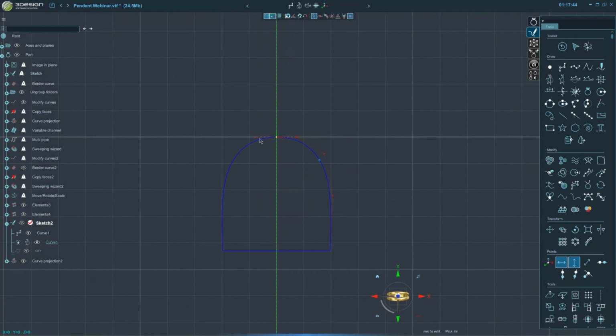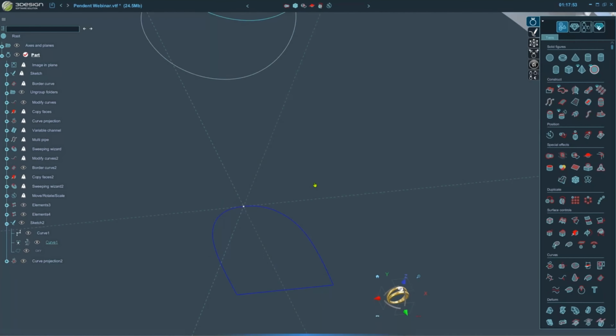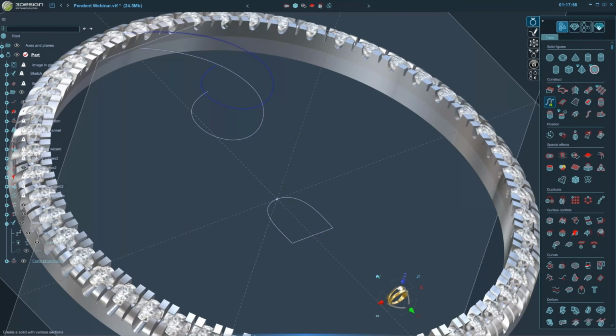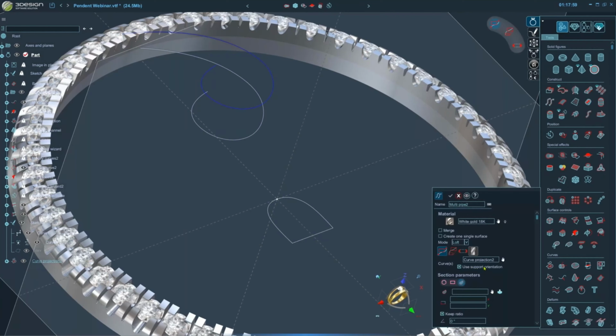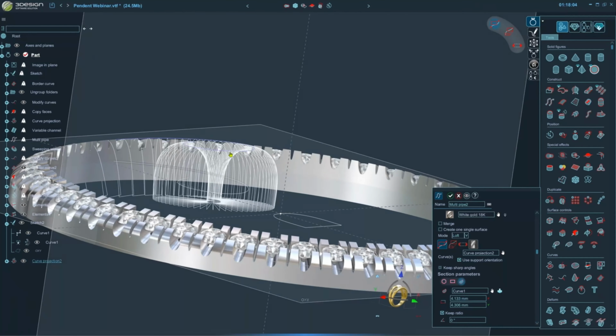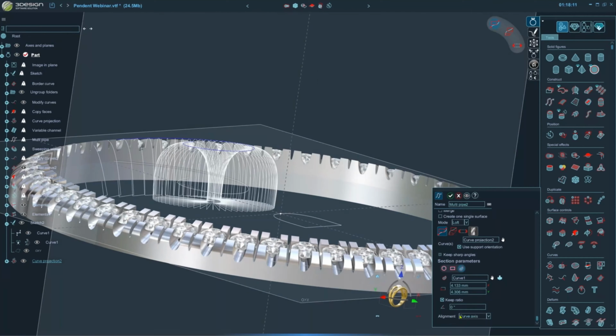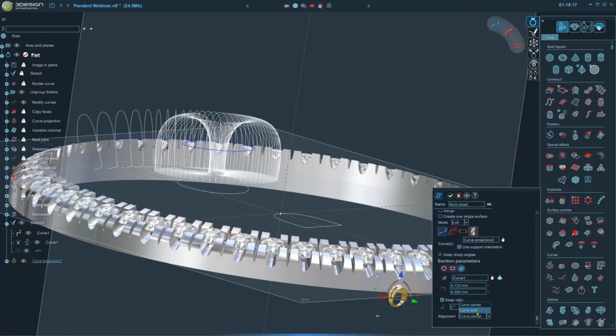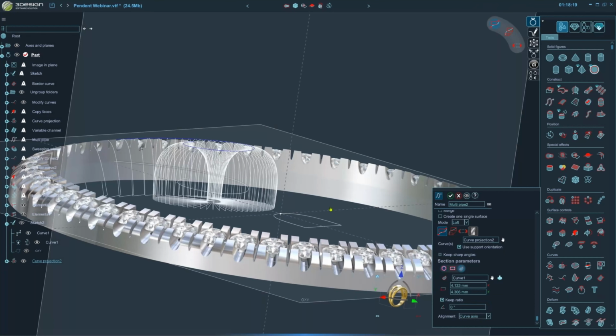So now the reference position of this curve, the 0 where it lines up to, is right at the tip of the shape. So you'll see when I go into my multi-cutter or multi-pipe, and I add my custom shape that is now translated to the right position, it's going to align it to the point that I had set. And that's where I have curve axis as the alignment. So curve center is the default. Use curve axis, it's going to use whatever point you referenced in the sketch. So a nice little trick for you for aligning your multi-pipes.